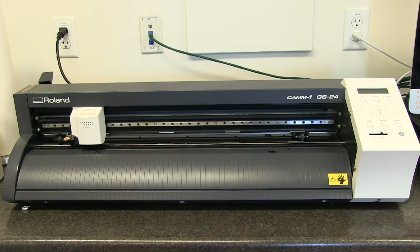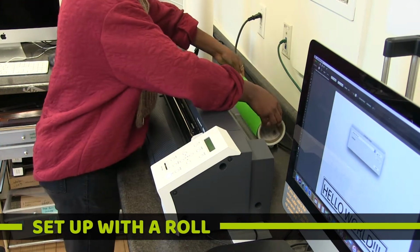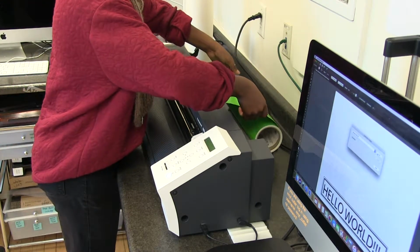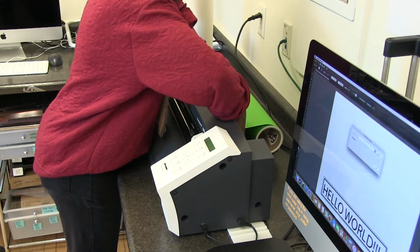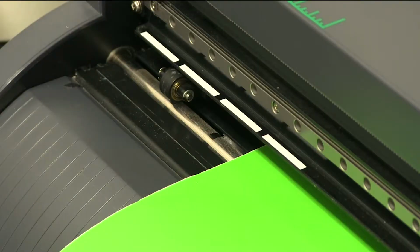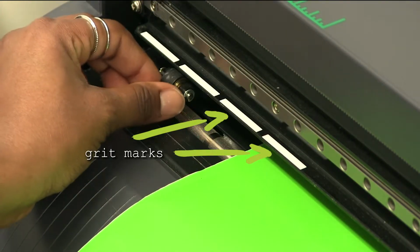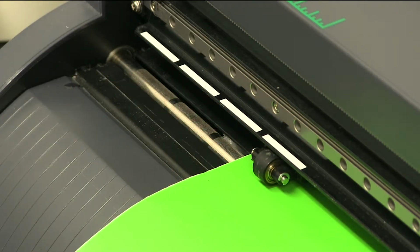Now we are ready to start and load the vinyl cutter to cut our creation. Load your roll of vinyl into the back of the machine. There will be some resistance to feeding the vinyl through the slot in the machine. This is normal. Ensure that your roll material is loaded properly with the pinch rollers positioned over the grit marks and toward the edge of your vinyl. Be sure that your material is parallel to the guidelines on the front of the machine.